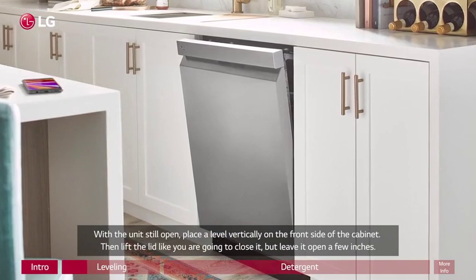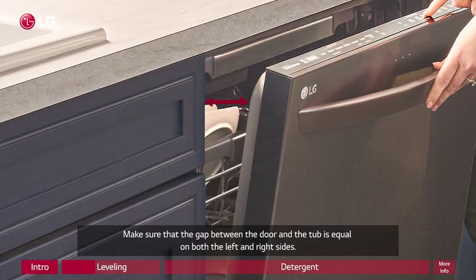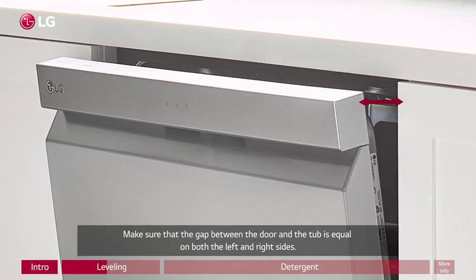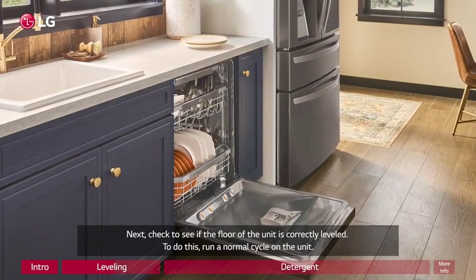Then lift the lid like you are going to close it, but leave it open a few inches. Make sure that the gap between the door and the tub is equal on both the left and right sides. Next, check to see if the floor of the unit is correctly leveled.